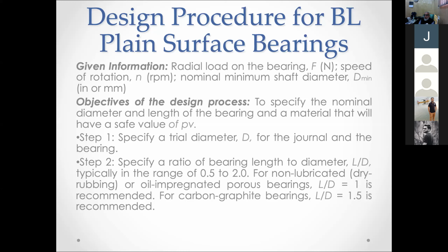Whenever you have to calculate the area, the projected area is different from the other areas of this bearing. So the projected area will actually determine the area of the bearing. If I open it, the projected area will be D multiplied by L. So if I open this bearing, this will be the projected area of the bearing. So the projected area is always diameter multiplied by length.